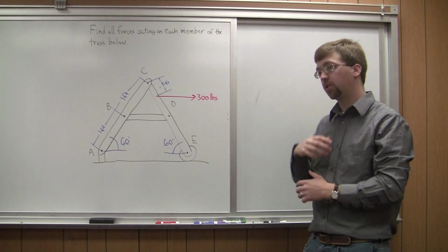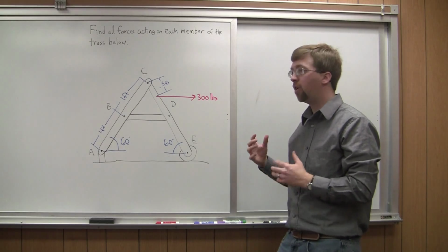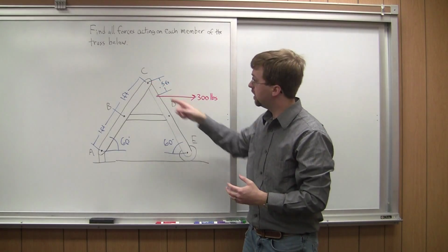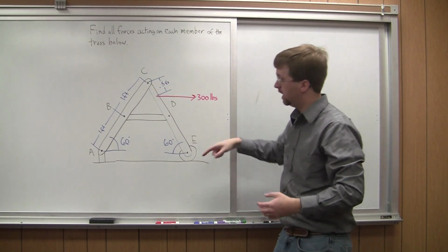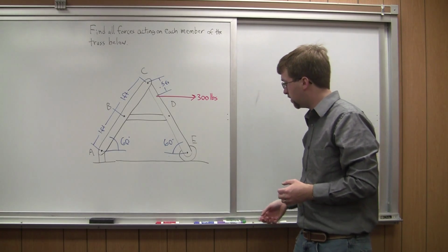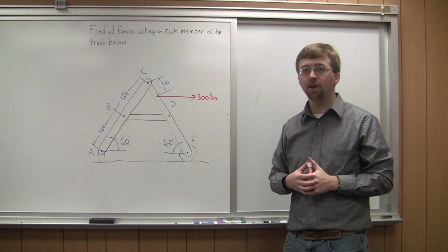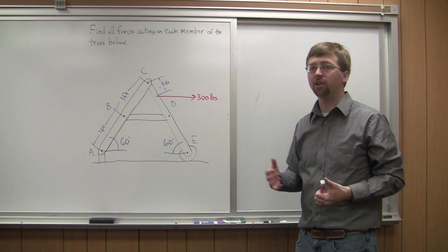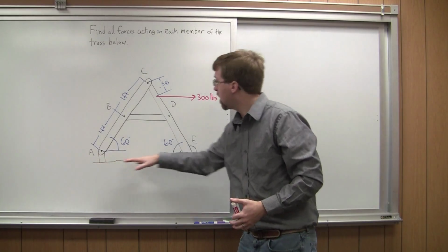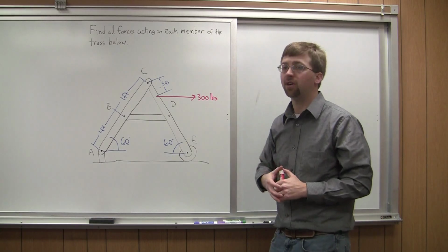So we're going to have external forces down here at the base that are acting on the A-frame. And then all the parts of the A-frame have forces experienced between the pieces, like at point C, where A, B, C and C, D, E interact. So the first step in any sort of problem is to see if we can analyze this structure as an independently rigid body. For that, we would separate it from the base, separate off the ground here, and draw a free body diagram of the whole A-frame structure.